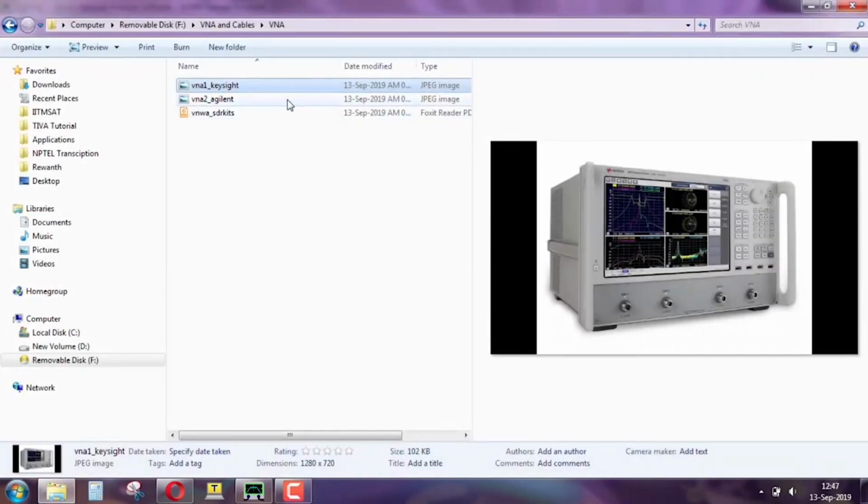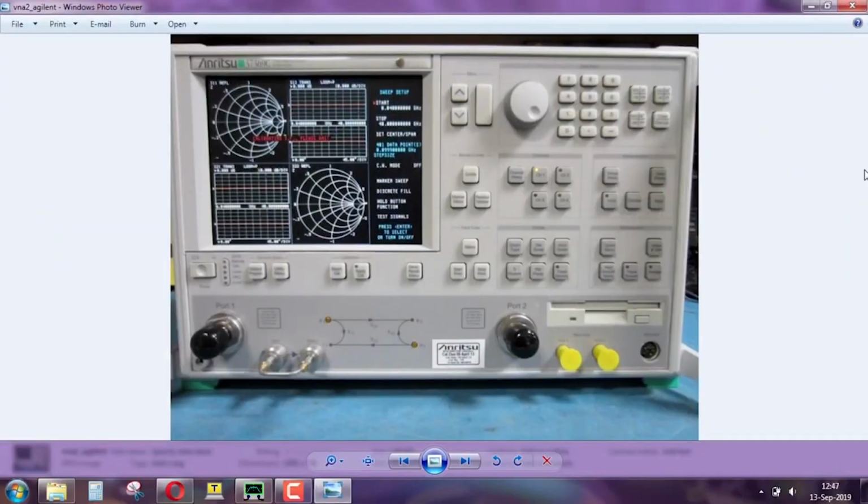This is another equipment from Anritsu, which is also a company. It just looks like this. I wanted to give you a feeling across manufacturers. It also has multiple ports, port 1, port 2. It also has different connectors, and it has Smith chart based plots. In theory, you could connect a transmission line, some impedances, filters, or different things that you want to make for these frequencies and analyze what is going on with these equipments. This is also probably equally expensive.